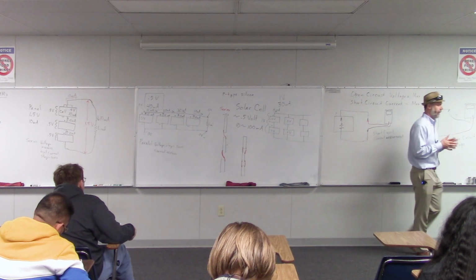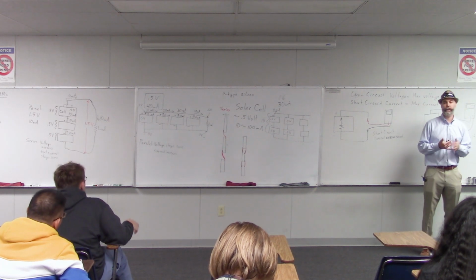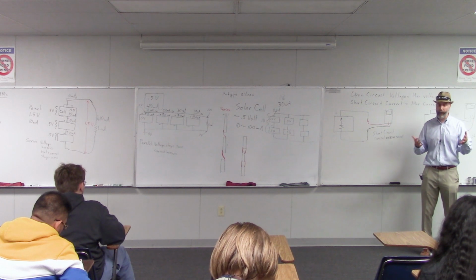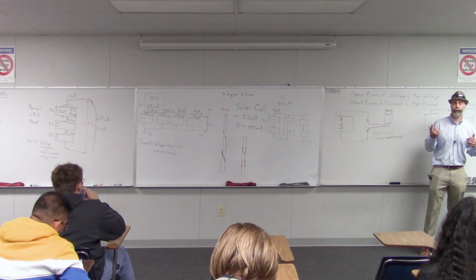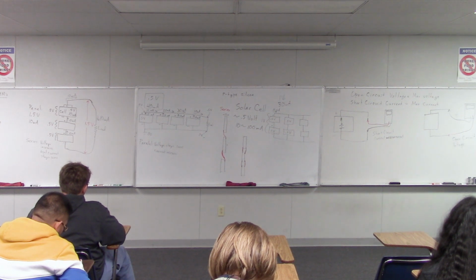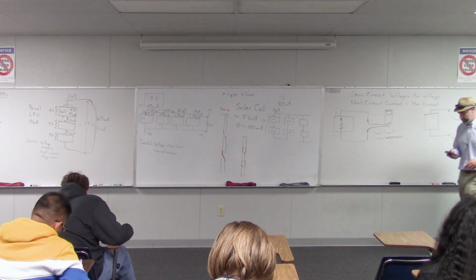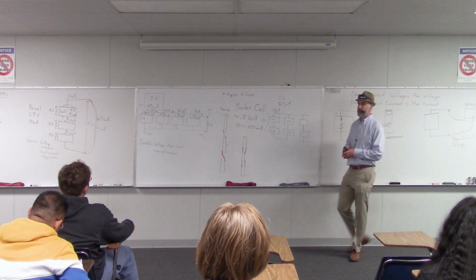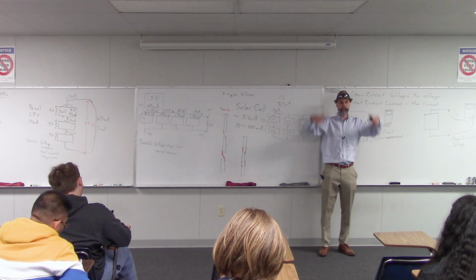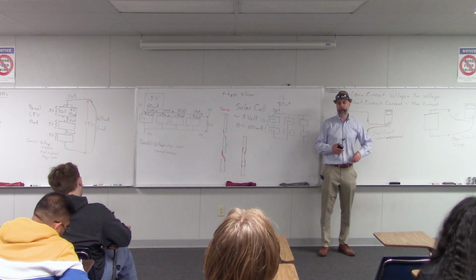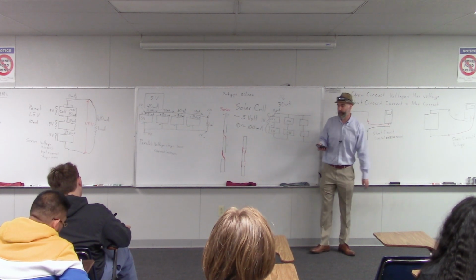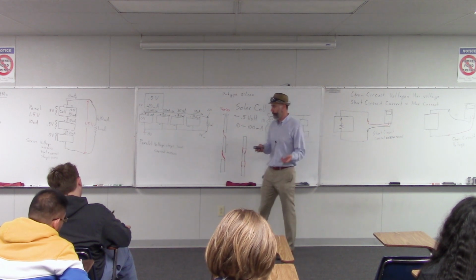So there are a number of things that affect how much energy a cell or a panel or an array can produce. Kind of the first and most important is how much sun is actually hitting it, and at what angle. So if you have your array out in a big open field and there's lots of sun, that's probably a good thing. If you got it up on a roof that's underneath a tree and it's in the shade, it's probably not going to get very much energy.